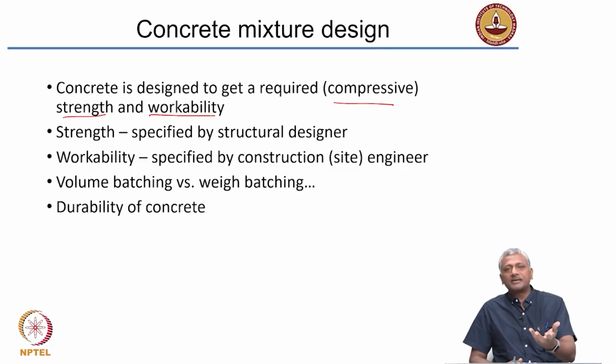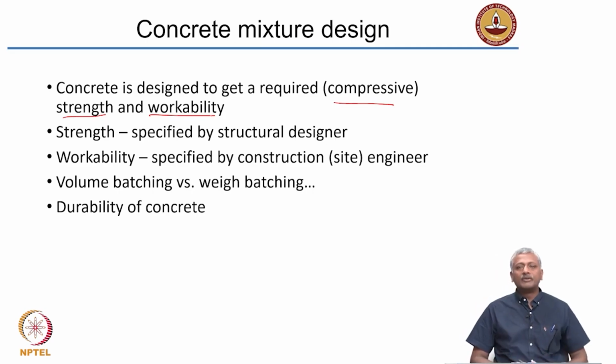Now you can compare this to something that you see at home when your mom does cooking, right? So when you have flour and you mix water into it, okay, if you mix just the right amount of water, the flour is nice and pliable. Okay. If you mix too much water, what happens? The flour becomes very sticky and starts flowing. So that's the same concept in construction also. If you add the right amount of water, you get the correct amount of workability. If you add too much water, the ingredients may start separating out.